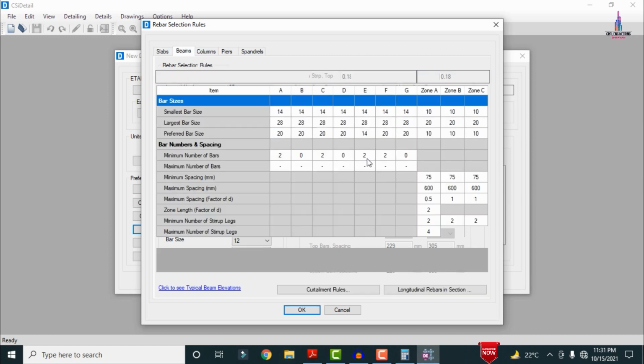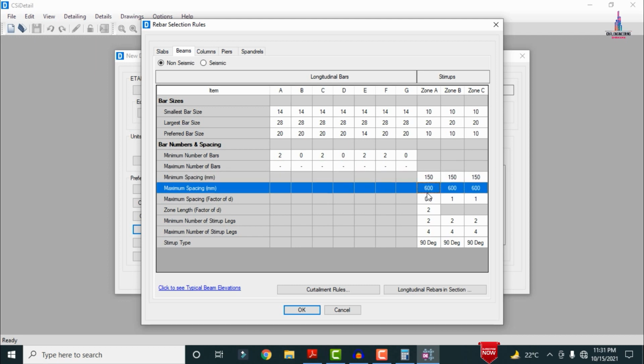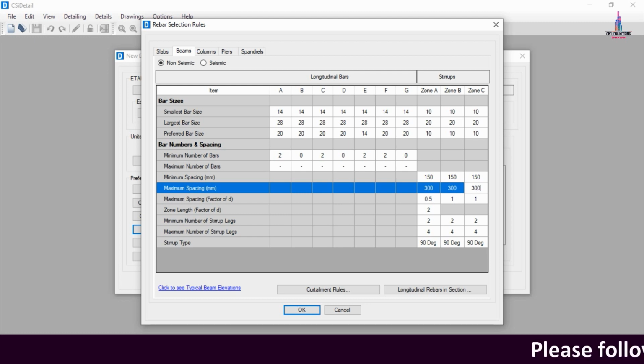This time selecting the beam option. So here I am selecting 150 for the respected minimum reinforcement section. Again I am selecting 150 under consideration. So now I am selecting one more section which is related to the 150, and my minimum spacing will come under the 300. Just I am considering here, 300. Again in the same process we have to change the value to the 300.